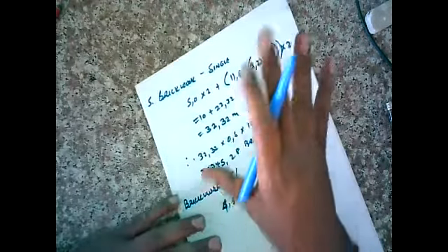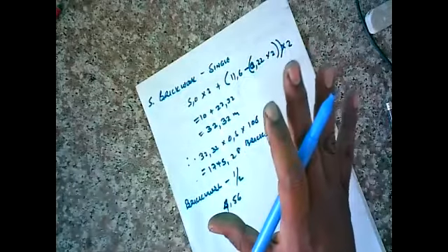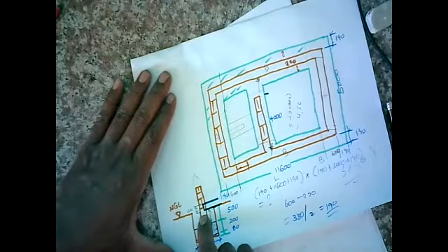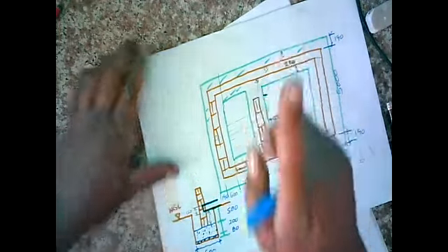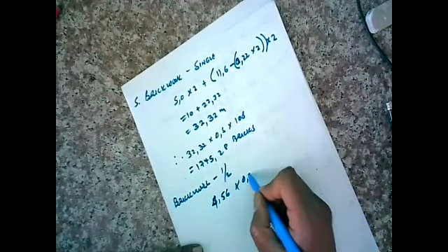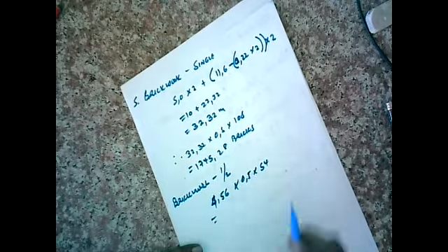I'm looking at the inner wall, right? We haven't come up yet, because in terms of the sketch, we are still down here, right? So I'm trying to find all the bricks from there to there, half brick, times 0.5 is the height, times, now it's half brick, so it's 54.